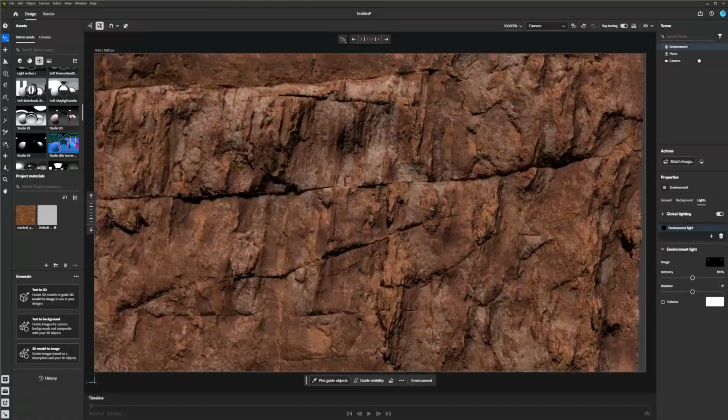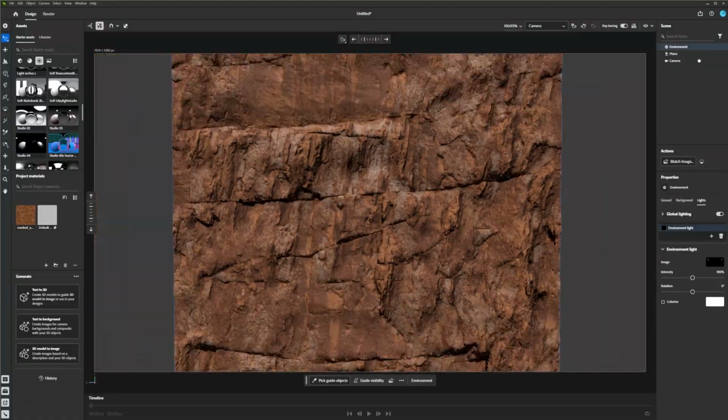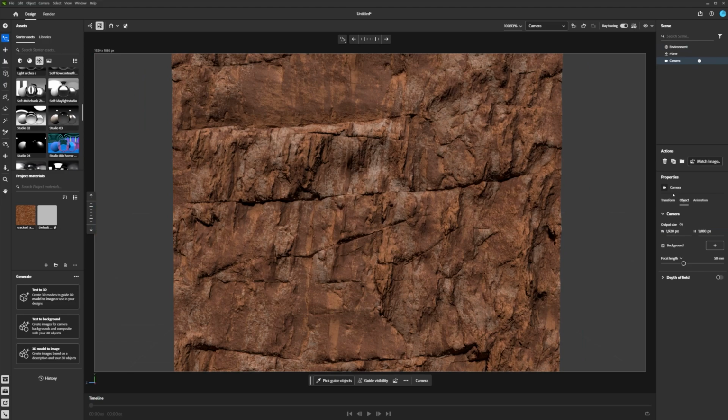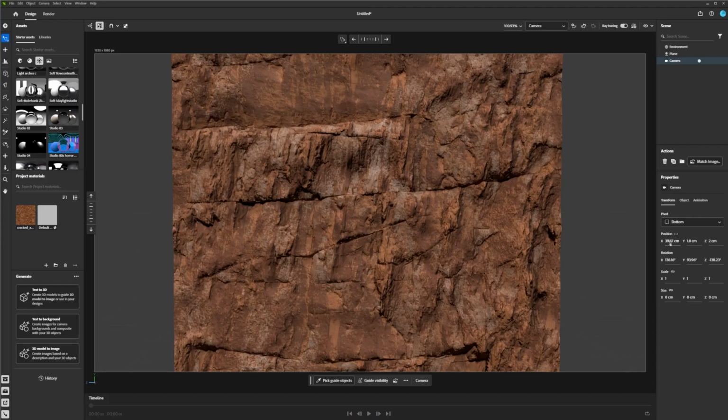I'll go a little more straight on, and generally I don't even like, you can in the camera settings go to exact position, say I want it exactly 90 degrees or whatever, so instead of 39 point whatever, I want it to be 50, make it perfect. I generally don't think that's a good idea, because the imperfections make it feel right, make it feel more believable. It almost feels cold and stale if you get things mathematically on top.